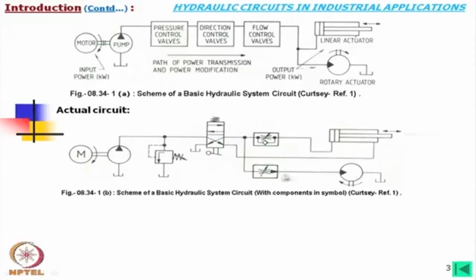Now, here this motor is in one direction, and oil is being returned directly to the tank. It is possible that we can move this as well as this, but depending on load we do not know which one will move, because oil will always flow to the least resistive path. Okay. So, this is just to show how this circuit can be designed.